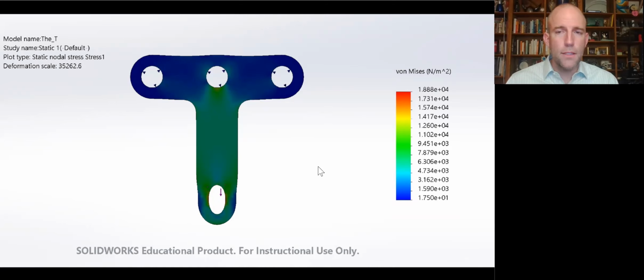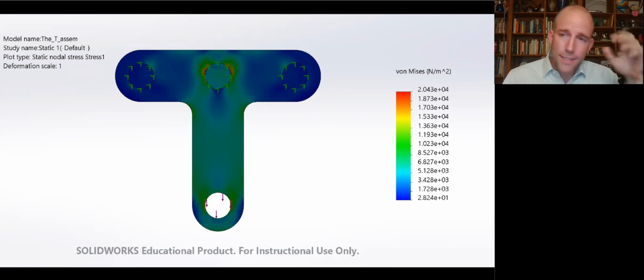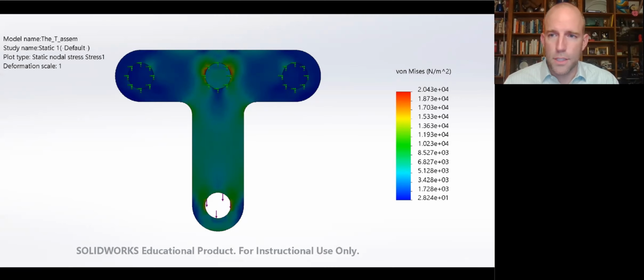Now, maybe you say, yes, if those holes are really fixed in space, that's like having the pegs be infinitely stiff, and this is all about deformation. So what if the pegs can move a little bit too? Well, if we model the pegs in an assembly analysis, now we've got the pegs modeled not as rigid bodies, but as deformable bodies in this FEA as well. Still, we see most of that force goes to the center peg.